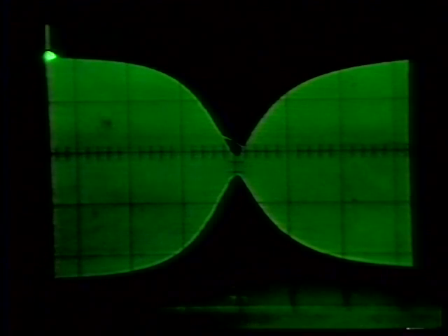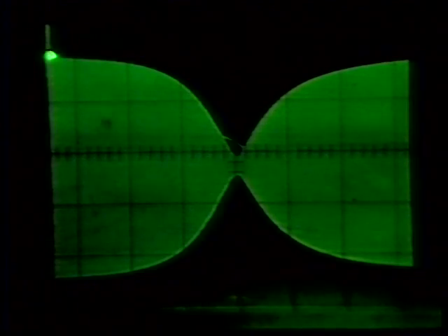There's just a little bit of noise in that trace. Let me erase the oscilloscope and do one final transient and see if we can clean that up a little bit. And there we get a fairly good null out of our rejection amplifier. Again, bear in mind that this amplifier only has a capability of getting closed-loop pole pair damping ratios of something like 0.1. We don't have a particularly large value for A0 in this experimental setup.